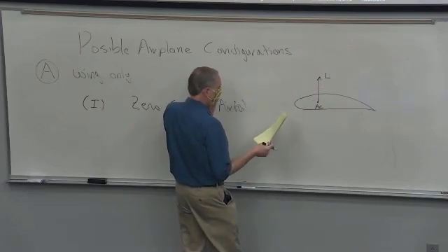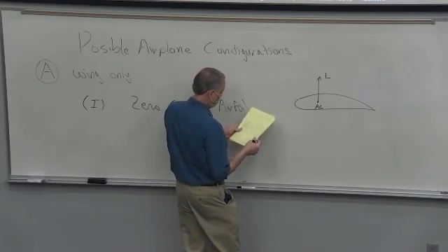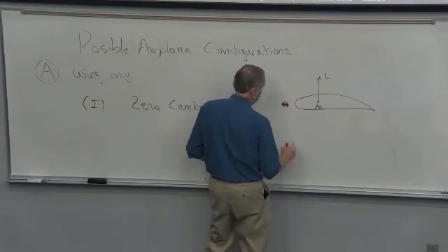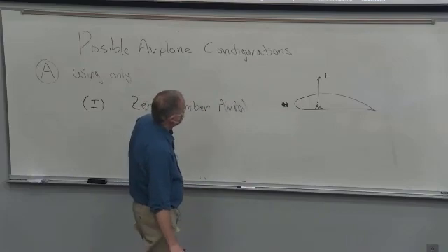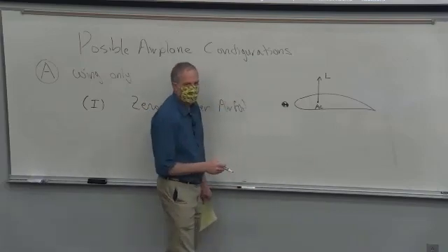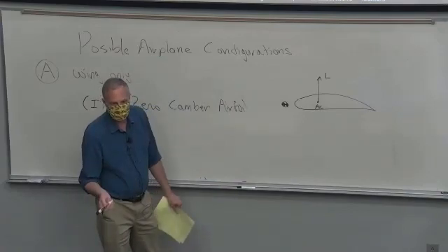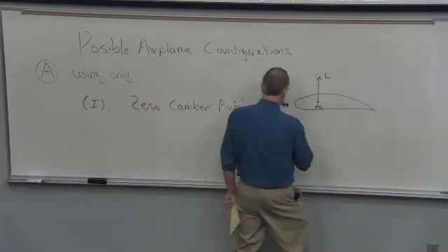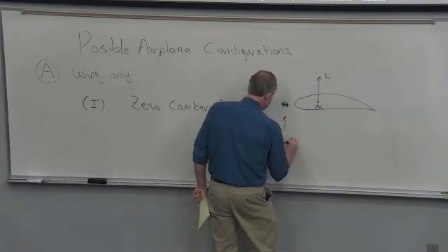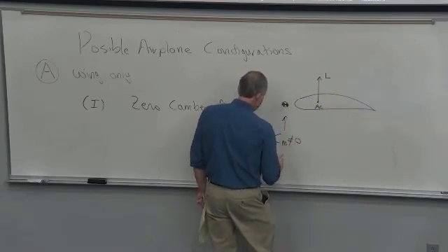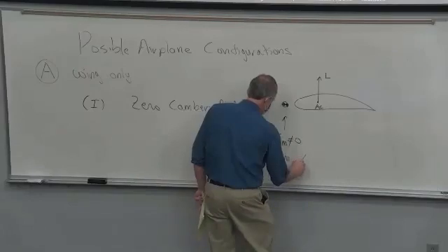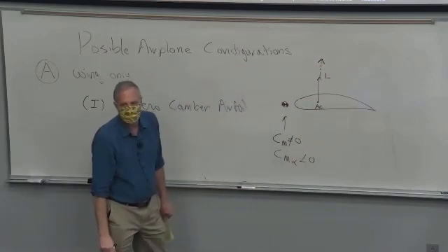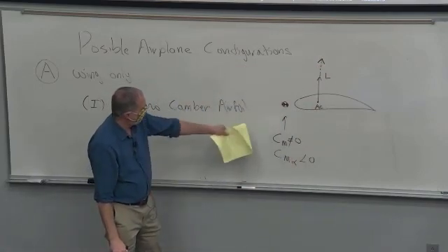So let's talk about, well, where do we put the center of gravity? We have the center of gravity here. Then the lift produces a negative pitching moment. For trim, we want the pitching moment to be 0. So that doesn't work. So with this position, CM, or the pitching moment, is not 0. We do get stability, because if the lift increases due to a gust, it's going to nose down and reduce that alpha back. But we can't trim, so there's no trim.